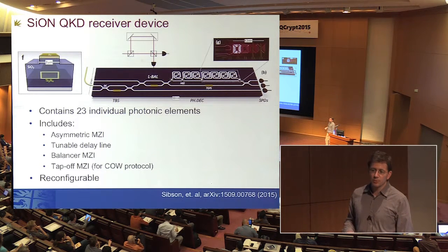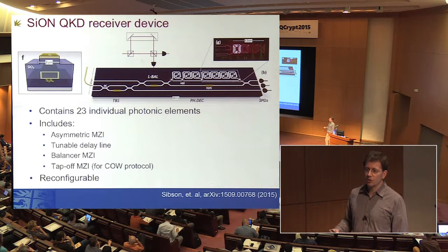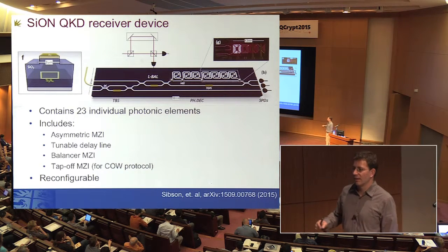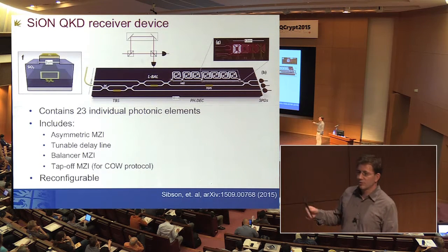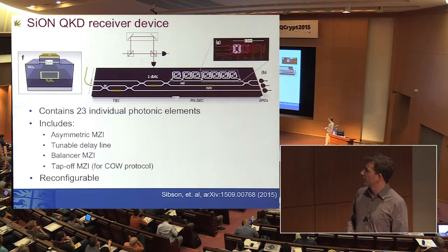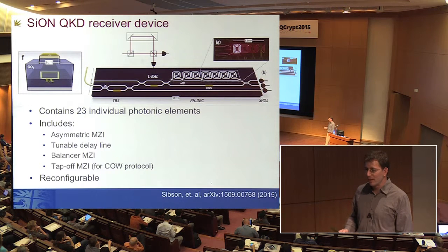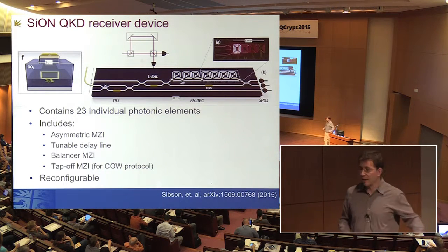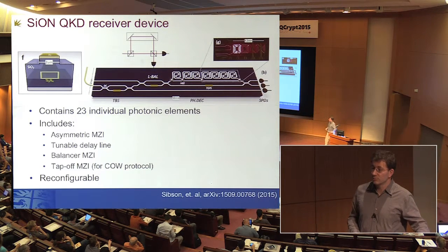It is possible. There are proof of principle demonstrators of on-chip isolators. The problem is you need to have effectively a material that has a magnetic susceptibility that allows you to have this kind of non-linear bidirectional interaction with the light, which is a very difficult thing to realize. So people have realized them, but they're lossy and they're not very practical and they're not readily available. So we have absolutely no plans to put isolators into these systems.